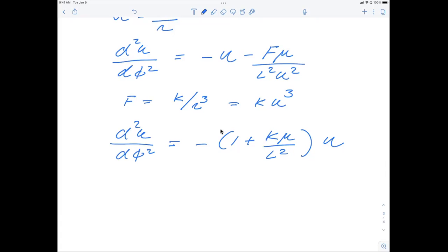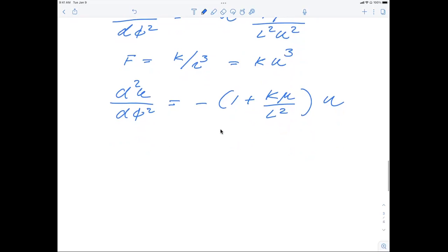So let's look at the analytical solution, because when we have it, it's going to be easier to understand. And I think that's exercise 1E or 1D. I don't remember exactly which one it was, the first part of the midterm. So if you look at that one, we can now just sandwich this into a constant. And we could call this our natural frequency again, because we have divided by the mass. So this could be our omega 0 squared, right? This is just a constant. So it means that we have an equation of this type, minus omega 0 squared times u.